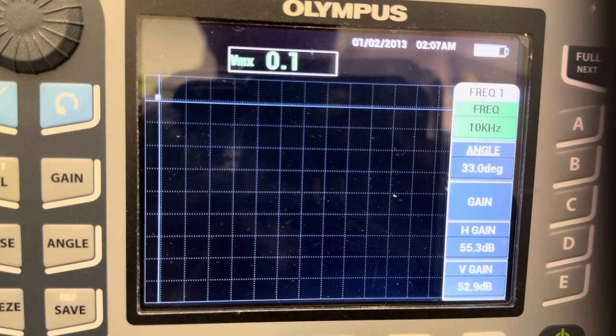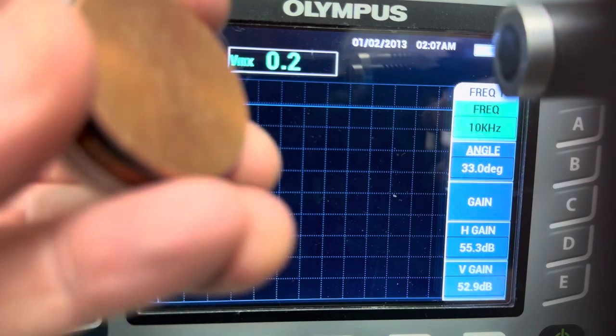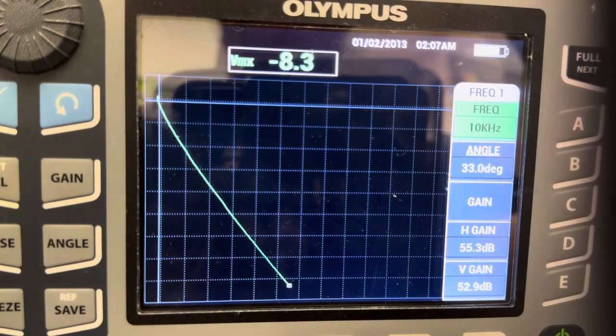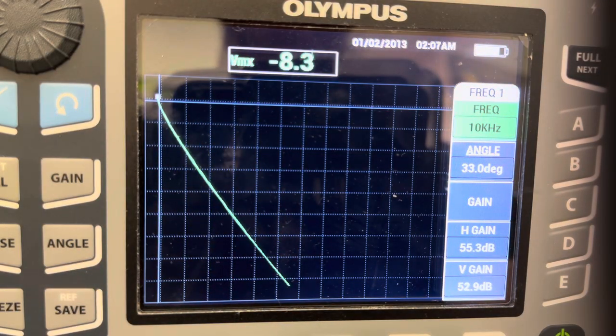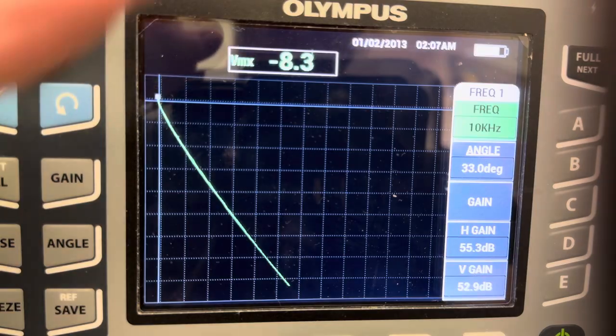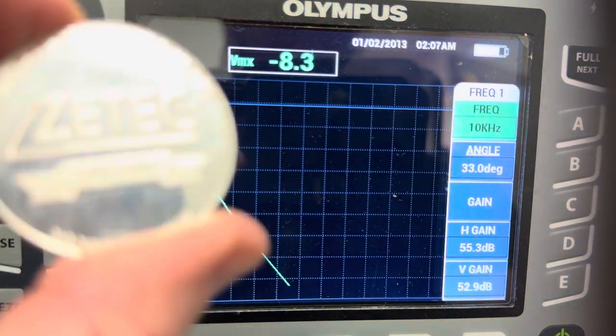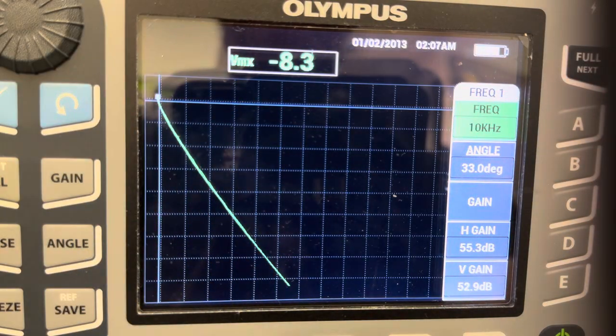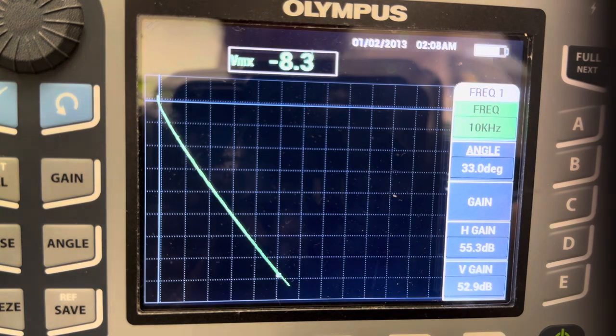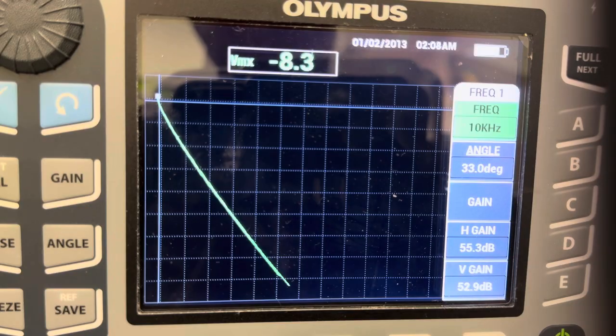Let's try to separate the variables from two high conductivity materials. Let's try that copper and the silver, because we couldn't separate them with the high frequency. So let's try 10 kilohertz on the copper. All right, that looks good. And we'll try the silver. I didn't give this a trial run, so I'm not sure how it's going to work, but it'll probably be separated more than it was with the 2 megahertz. I stand corrected. Still can't tell the difference between those two.